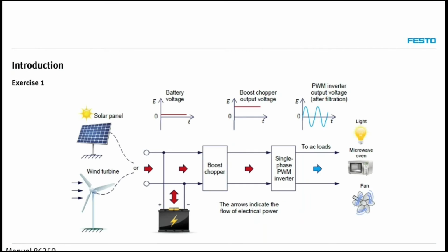Okay, so as I was explaining to you, the battery only produces about 48 volts typically, while on the DC bus side here, the voltage that we require to be able to produce an AC power of 220 volt, or 120 if you're in North America.